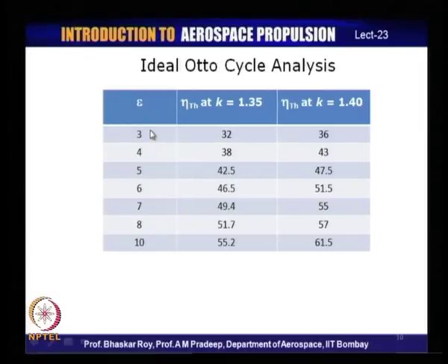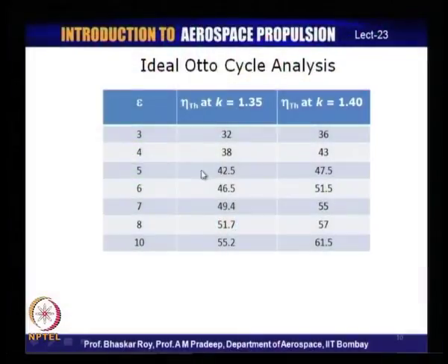And that gives us an idea to what extent you can have high compression ratios to get higher and higher energy efficiency of the engine. What the compression ratio can be depends on a number of parameters or a number of practical considerations, and we shall be talking about some of that as we go along in this lecture and in the next lecture. So, the cycle designer has an idea now that if he chooses a certain compression ratio and given the working medium, he would be able to attain a certain kind of cycle efficiency, which he hopes to come pretty close to in an actual working engine.